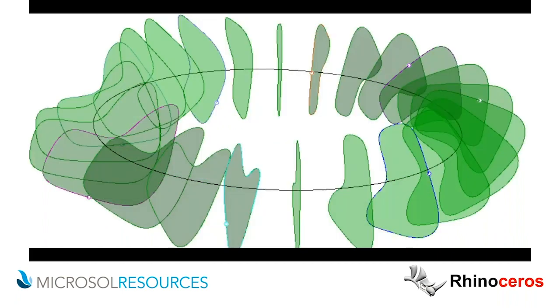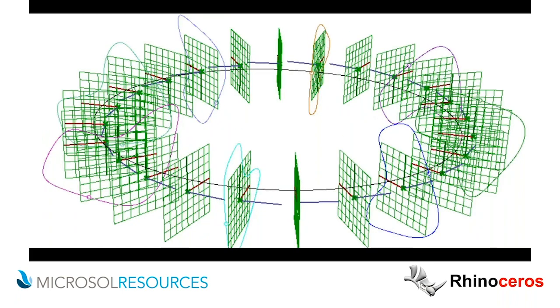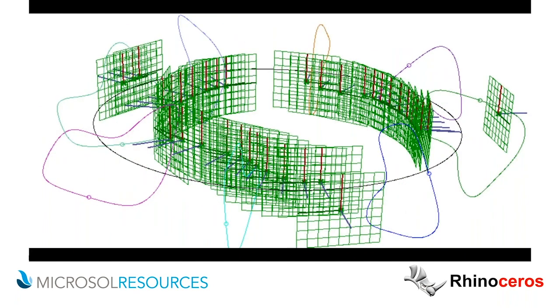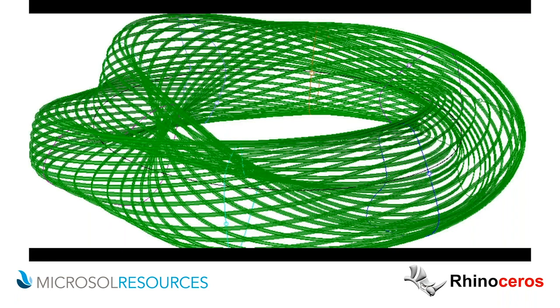So lofting that curve and creating this curved structure from it. So that's just a few of the examples of the capabilities of Grasshopper within Rhino. Really, the possibilities are endless, and you can use it to automate any process or general 3D geometry that you might use frequently, doors, windows, etc.